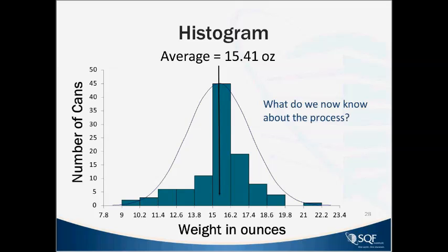I'm not going to comment too much on the breadth of the data at this point in time. But when we see data like that, we can basically say the data presents itself in a normal fashion. We can say that that's normal and that the process is stable. If we get any different iteration of that, where it's all flat, it's not showing a peak and equal distribution to either side, we can make proposals that the process is unstable. If you have an unstable process, you can't consistently and accurately apply statistical process control.